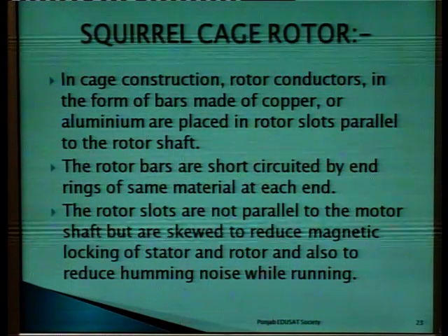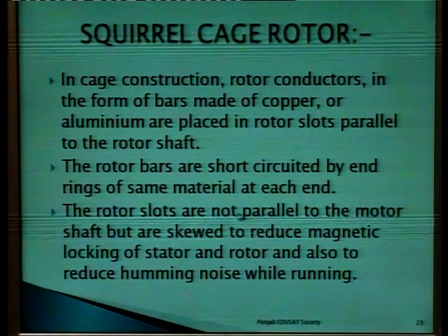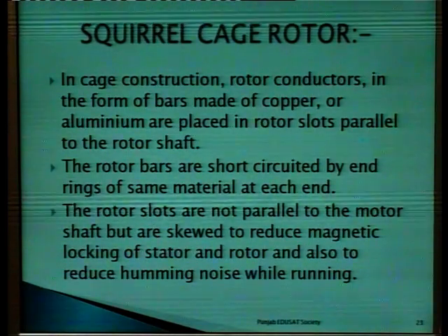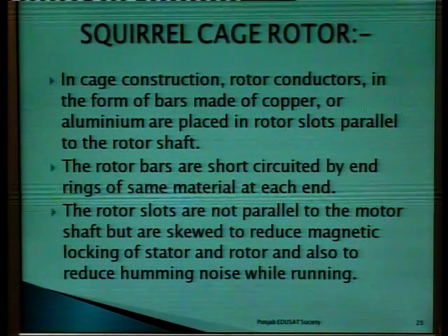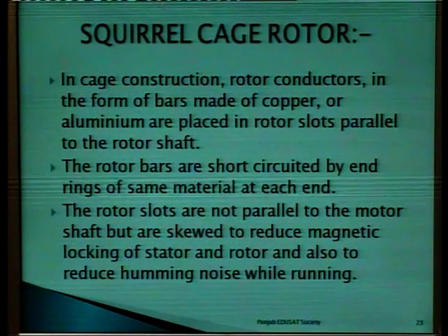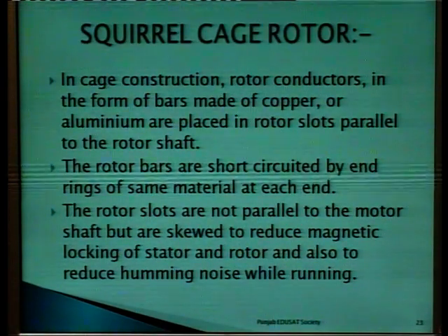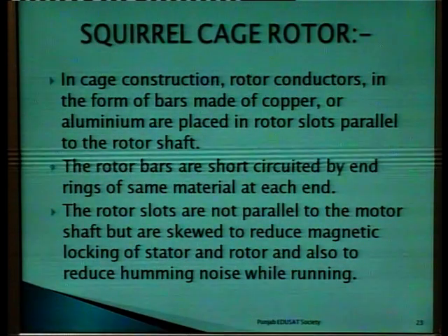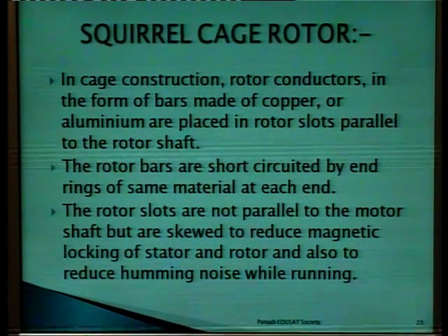So, the rotor slots are not parallel to the shaft of the motor, but are skewed to reduce magnetic locking of stator and rotor, and also to reduce the humming noise while the motor is running. This is the particular special point to be noted here.